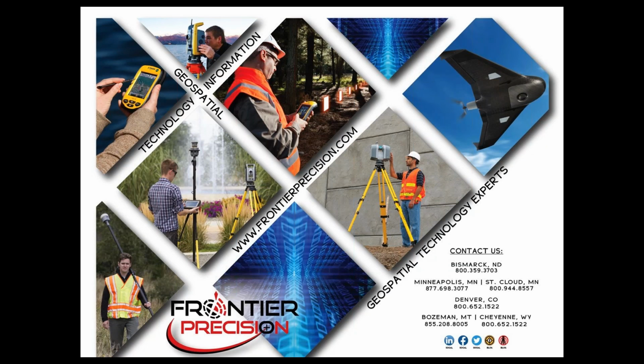It says, when you edit a station elevation, does it change the keyed-in string elevation or just the stakeout? From what I understand, that affects just the stakeout. It doesn't modify the actual road alignment itself or the actual string line itself. It's just a one-time entry.